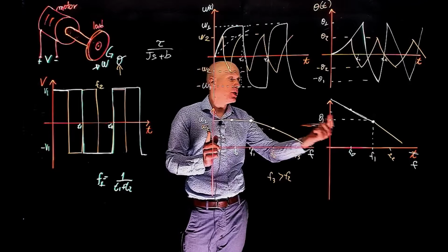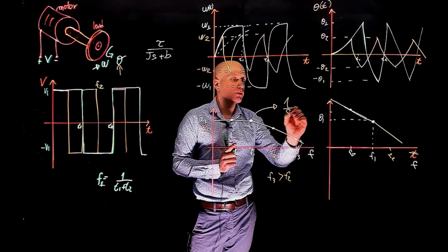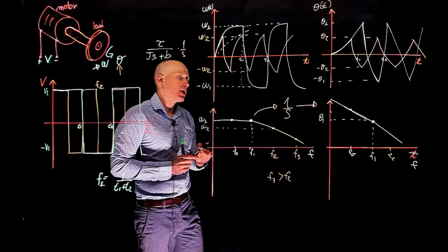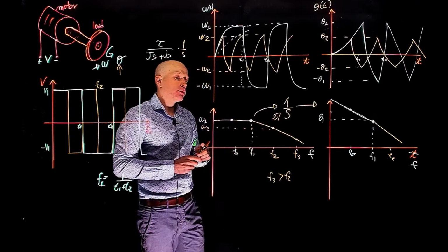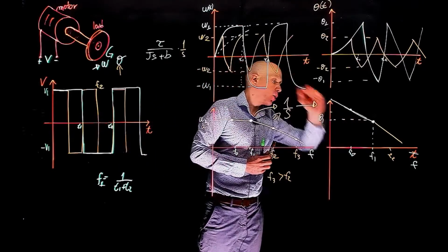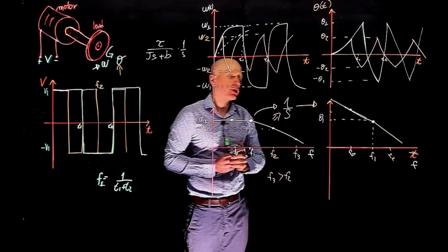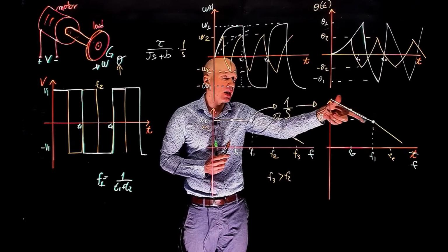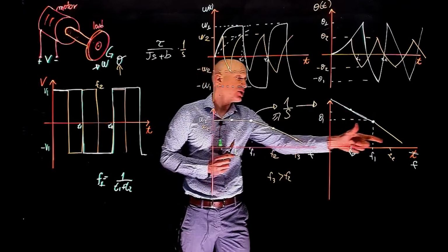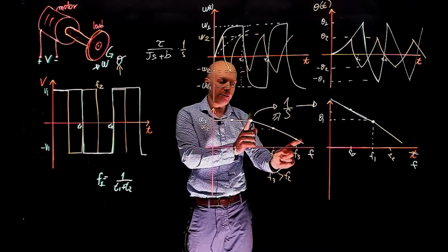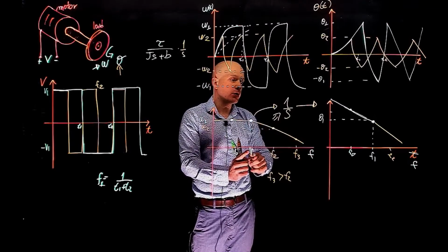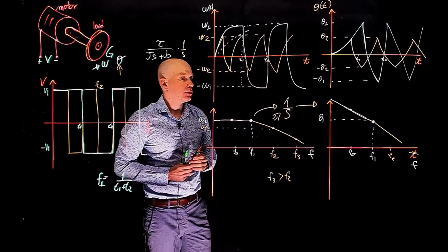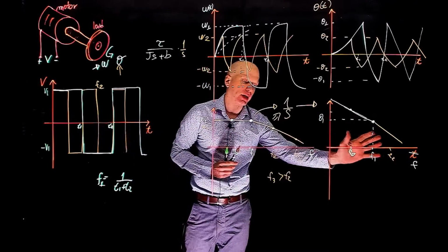speed. If you want to go from speed to position, what do we do? We have to integrate it. And by doing this integration, we are actually multiplying this function by 1 over s and adding a pole at the origin. This pole at the origin adds this slope that is now constant throughout the entire frequency spectrum. And that's why now the slope that was 0 became non-zero here. We know that this is negative 20 decibels per decade. This slope just increased. It increased because we had the effect of the inertia and friction that resulted in this cutoff frequency, which is again there, but now in addition we have that slope created by the pole at the origin, which is the integration reflected there.